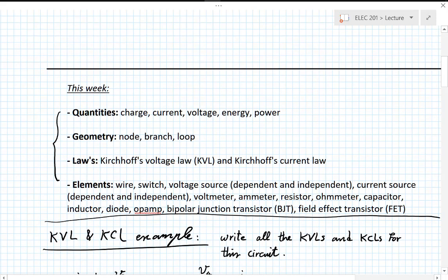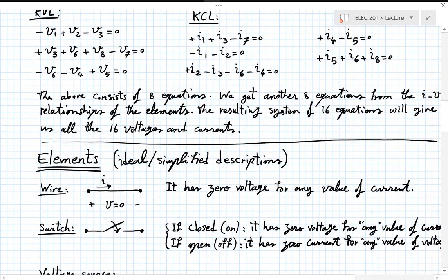So the question is, if V equals Ri and R is infinite, does that not mean that V will be infinity, which we said is not a good thing, right? It will be unless I is 0, right? So in a voltmeter, V is a finite value. I is 0, and R is a finite value divided by 0, which is infinity. Or I is a finite value divided by infinity, which is 0. So there's no contradiction.